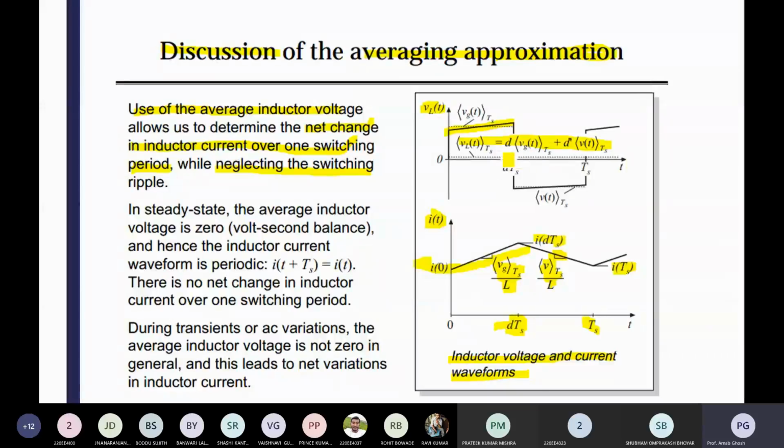Basically, the positive and negative cycles of inductor voltage are equal in amplitude, meaning area. You can say that energy storing and energy relieving are the same, as per the convention. So the average value should be 0, but it has a very small bias value. That is why it is written as nearer to 0, not exactly 0.